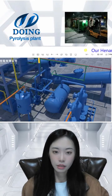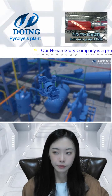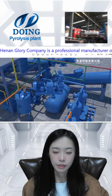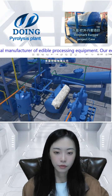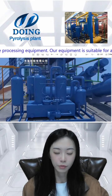And then this is the micro pressure. You can see here the micro-negative pressure process to reduce the contact of the carbon black and flue gas. And then we will have a water seal to prevent the tail gas from flowing back upwards.